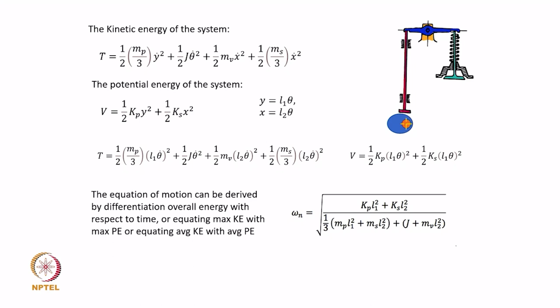we have to do inferencing, right. That is what we said. Once you get to solve for natural frequency or vibratory response, how do we make sense out of this outcome, right. So, I would suggest that you use the numerical values which are given in the previous slide to obtain the value of omega n, and then what has been asked or what has been indicated in the example is that either you find the value of the spring stiffness here Ks, so that this resonance is kept 20% away from the engine idling speed.